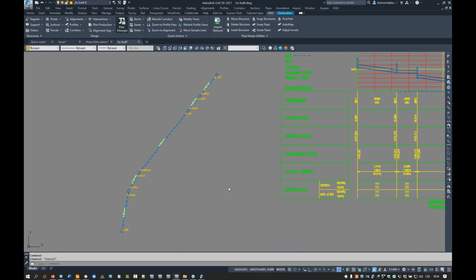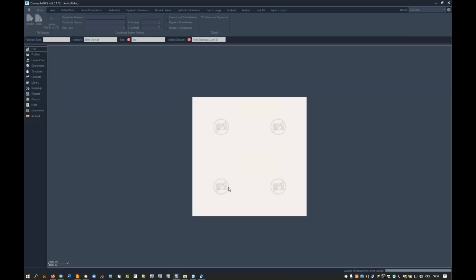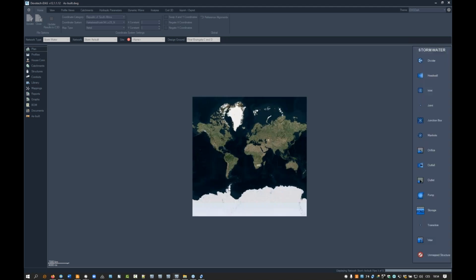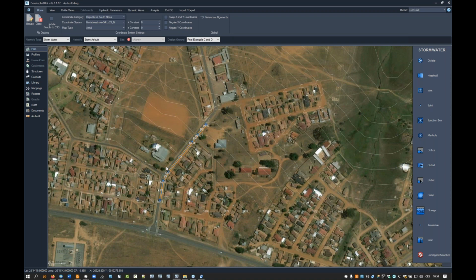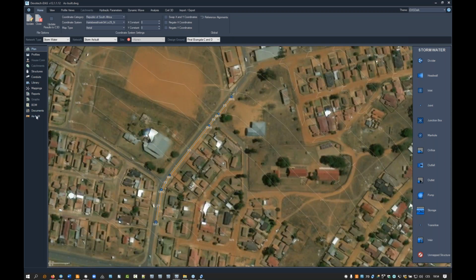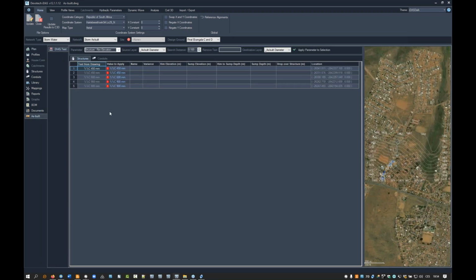and I'll show you how you can quickly do this. Of course, you must create a pipe network first, but you can use the wizard, create pipe network from polylines, and then you can assign elevations from those text objects. Let me go to the as-built tab. So this is the pipeline along the road. Let me go to the as-built tab, and here it is.